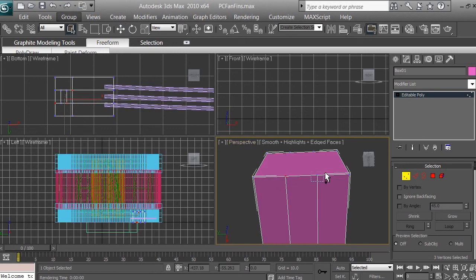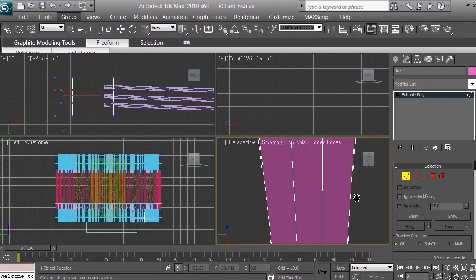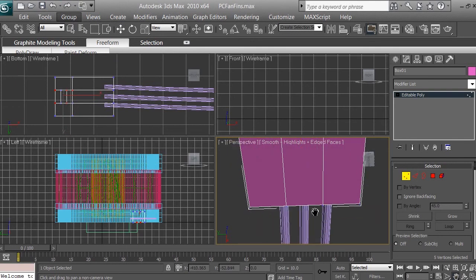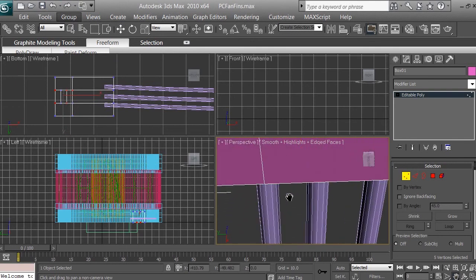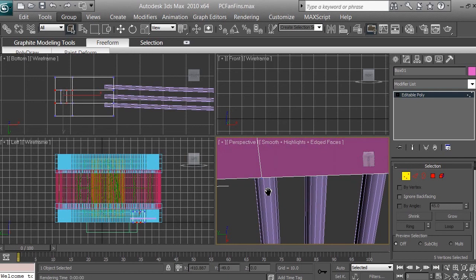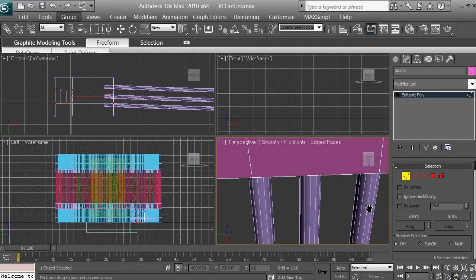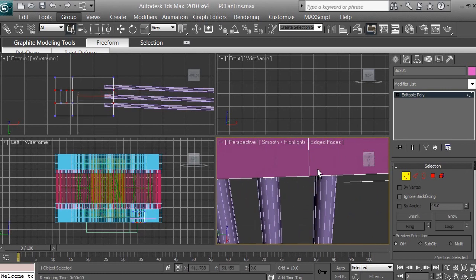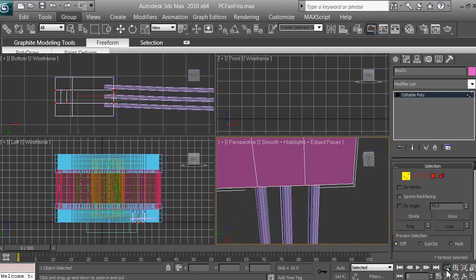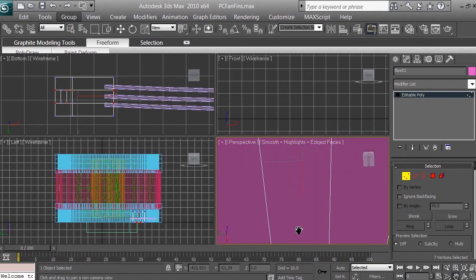Okay, so when you're selecting the vertices, you have no ability to move them, to screw your model, and those bottom vertices as well. By holding the control button, you can see that plus by the mouse icon, and this one right here. So I'm selecting those 4 vertices. Let's zoom out and bring it a little bit to the top. You can see bottom selected, top is selected.